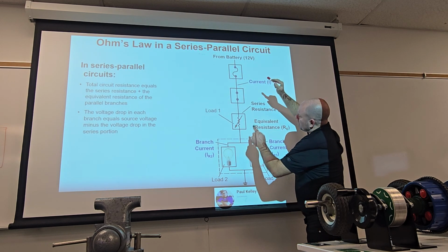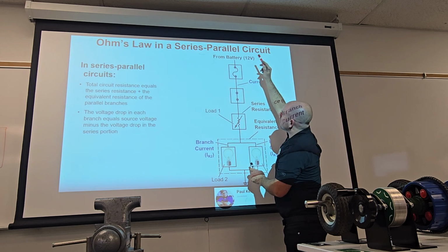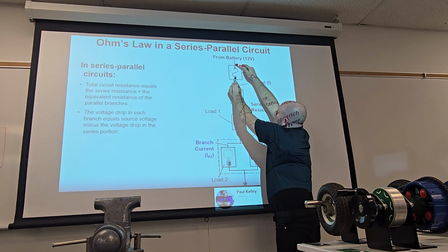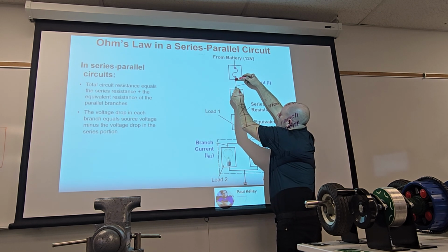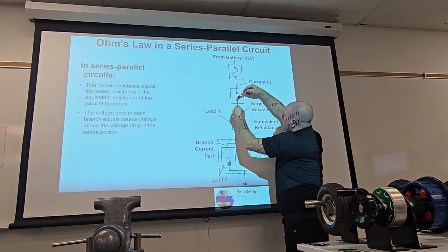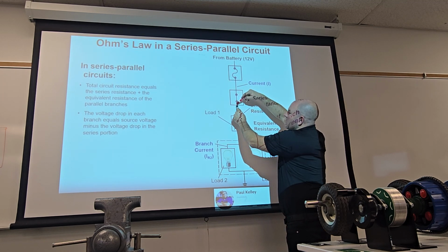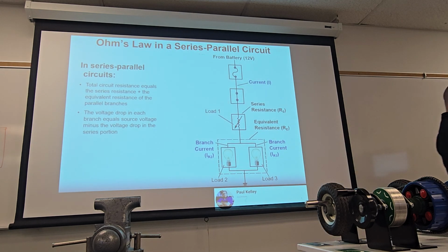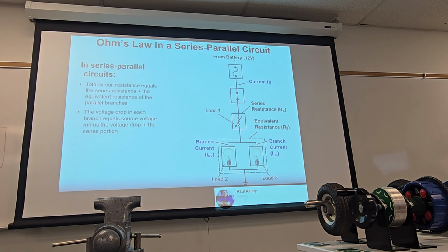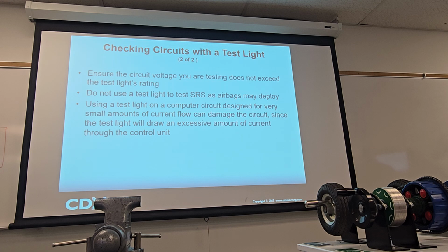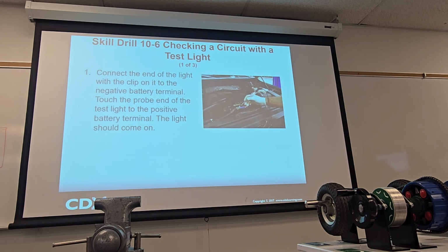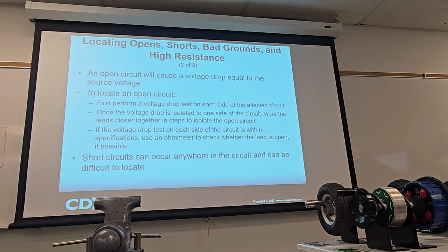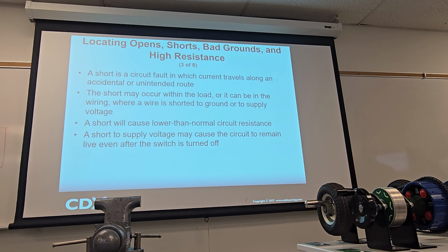So we're gonna determine, if it was 0 volt drop, 0 volt drop, 0 volt drop, 0 volt drop, 0 volt drop, 12 volt drop at the connector coming out of the switch, then you got it nailed down. You know it's that connector, it's that male-female terminal coming out of the switch, then you could do it. Then you could fix it. Or at least sell the repair, okay?